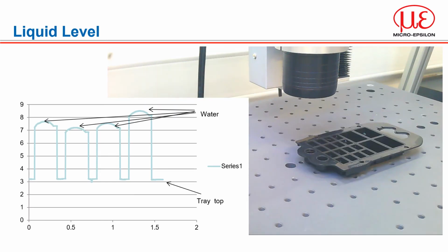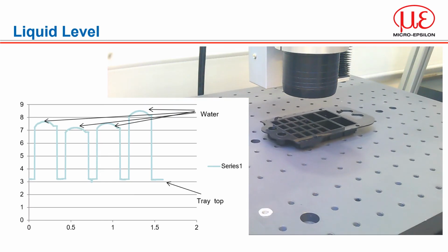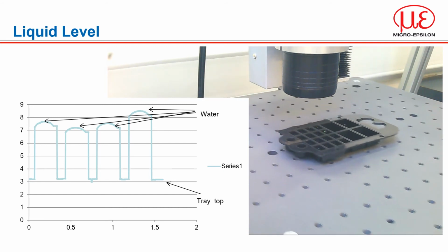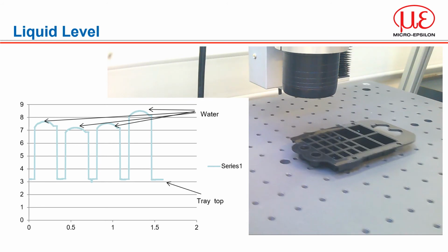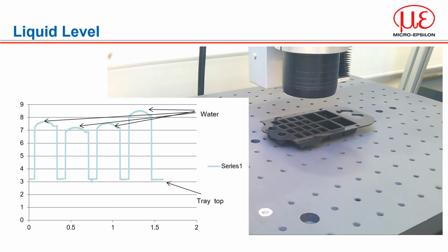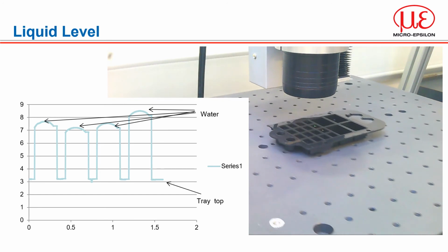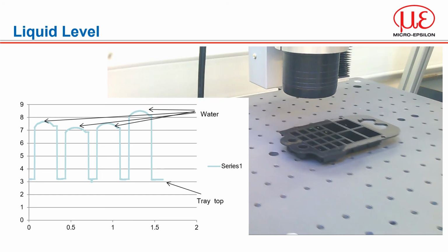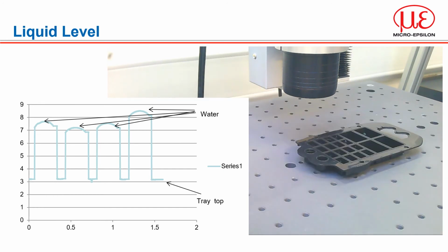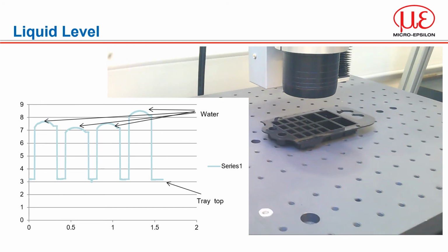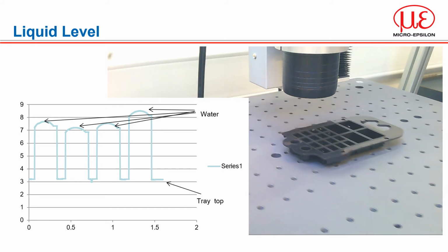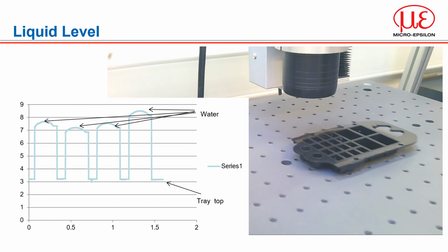Confocal chromatic sensors are used in pharmaceutical and medical technology. An interesting example is the measurement of fill height or level in medical laboratories. Here, active agents are manually filled into micrometer tubes for batch testing. It is essential to measure the quantity of each agent precisely. The confocal sensors scan each micrometer plate in succession, and the system measures the distance from sensor to liquid to micrometer accuracy.